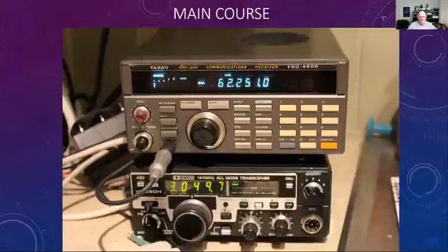Okay, so this is what I used to use many years ago. This is a scanner. It's an old, ancient, battered and bruised FRG 9600. This was about £500 in 1980-something. And it's actually tuned to one of the, well, that would be Iceland. At the time I used to use the Iceland transmitter on 62.251 megahertz, upper sideband.